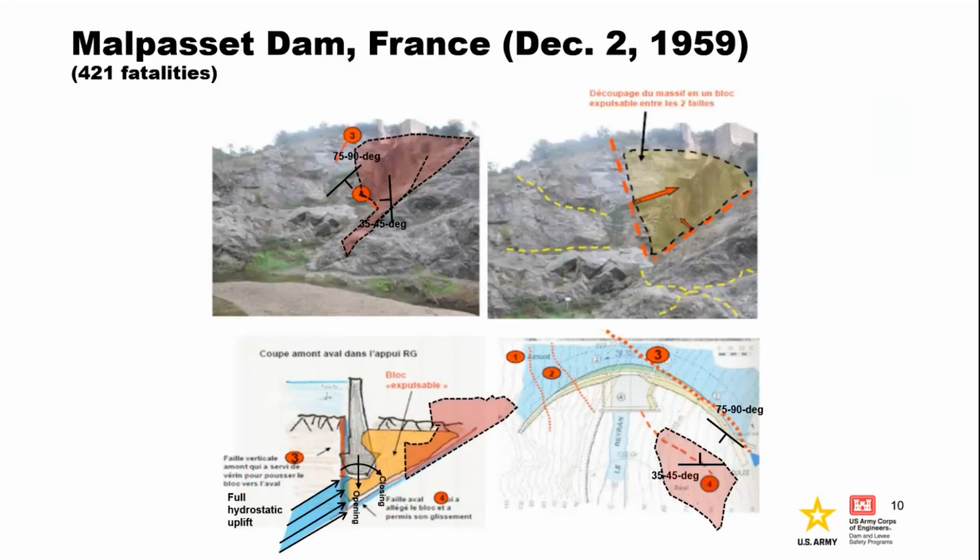As the reservoir water rose, the loading increased until the rock block began to move. The arch tried to redistribute the loads higher to the thrust block, but under the extreme overload, that block moved about 3 feet downstream and separated from the abutment, and without anything placed to transfer that load, the entire left side of the dam lifted and then rotated downstream until the dam ruptured. So it basically just lost its support and slid downstream.